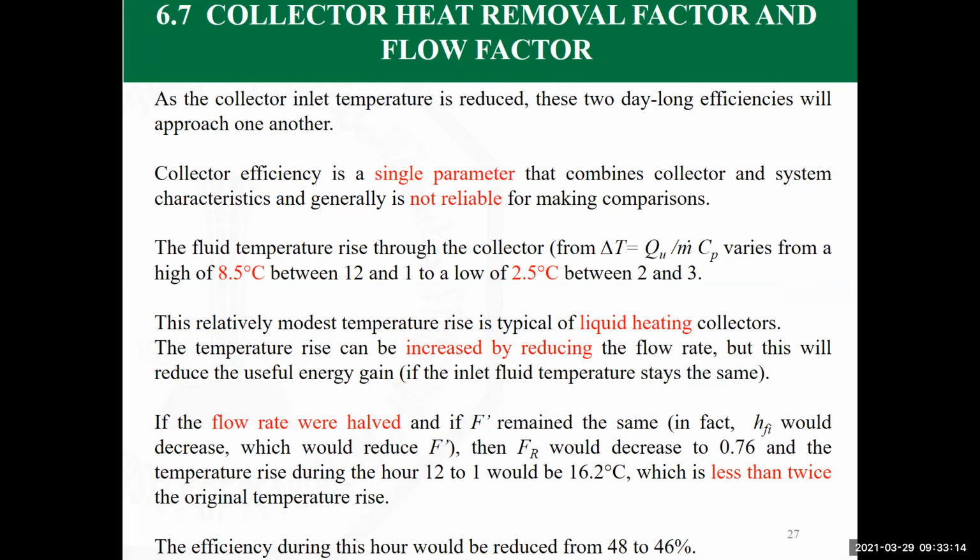And this is something that we have seen a lot in our experiments when we are dealing with solar energy. I use solar collectors a lot in water desalinating areas. And one of the technologies for desalinating the water would leave that choice for us. Do we need to heat the water or heat the air? Heating the water, the delta T is not large. But heating the air, it's very easy to get a collector and raise the air temperature very quickly to a high value like 100 degrees or sometimes more.